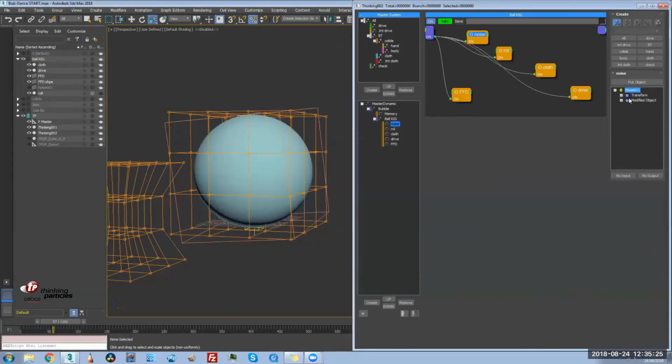So let's start to assign some controls. On the noise, we want to control the scale and the strength and the velocity of the noise. As you can see, the velocity is invisible. This is because the noise space warp is legacy Max stuff. It comes from Max 1, release 1. So not everything is really well supported inside paramblock, but it will work. It just misses the name, but it will work. So don't worry about that.